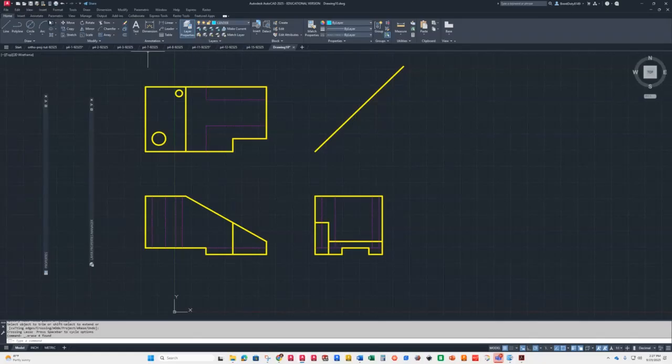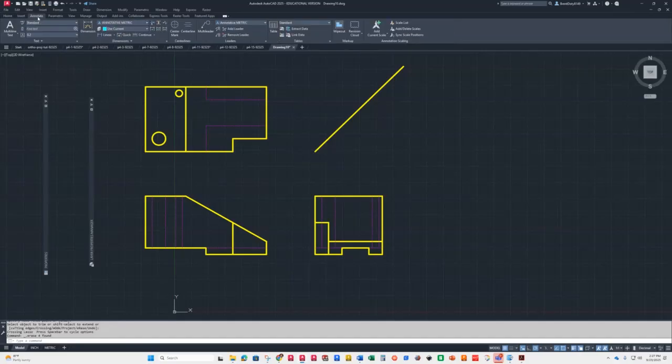So we'll go to center and annotate. Okay, so this is the other one where you need to type in center exe. So you're going to type in center exe to change this to at least 3. But here's the thing. Since you're going to scale this thing down 1 to 4, so it's going to be quarter size, you could actually multiply the 3 that it would normally be. So 3 times 4 would be 12. So let's see what 12 looks like. It may be too big, but we'll try it.